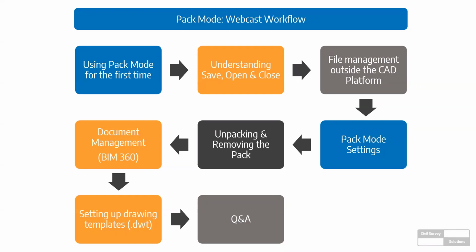Then we're going to look at some of the advantages that pack mode gives you in respect of file management with your DWG: save as, copying, and renaming within Windows Explorer, which normally we would say you've got to work with the data folder and there's a bit of work to be done there. We'll show you how that can work, followed by the settings and some of the background content which you can choose to change or just leave, but really useful stuff in there, particularly when it comes to changing when the data folder is being unpacked or worked from. Unpacking and removing, we'll explain when we get there.